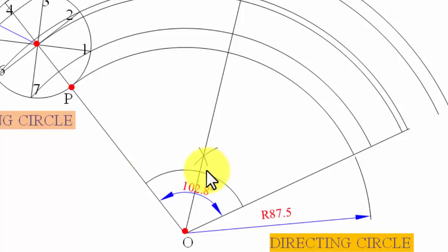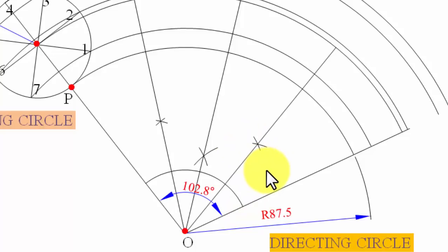So 2 can be made 4. All right, so keep your compass here, put an arc, keep your compass here, cut that arc. It's going to be looking something like this. Okay, same stuff has to be repeated with this as the center and with this as the center. With this as center, you need to make an arc. With this as center, you need to cut this arc. All right, now you can clearly see that this angle 102.8 degrees has been divided into 4 equal parts.